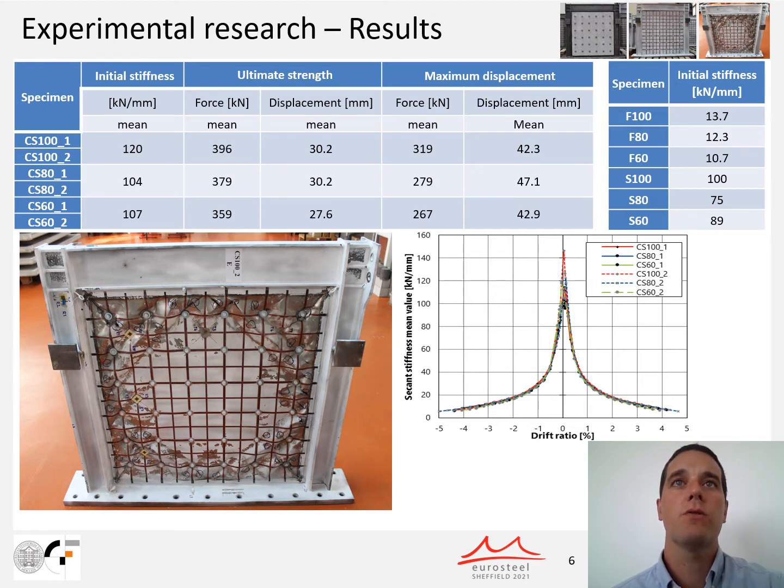After reaching ultimate strength, further increase of the displacement resulted in crack development at the corners of the steel infill plate, which propagated towards the plate center. Tension diagonals have formed only at infill plate corners, while the plate middle part remained almost intact. Final failure of the specimens occurred after the crack from the heat-affected zone at a connection between the column outside flange and the base plate propagated into the column web.